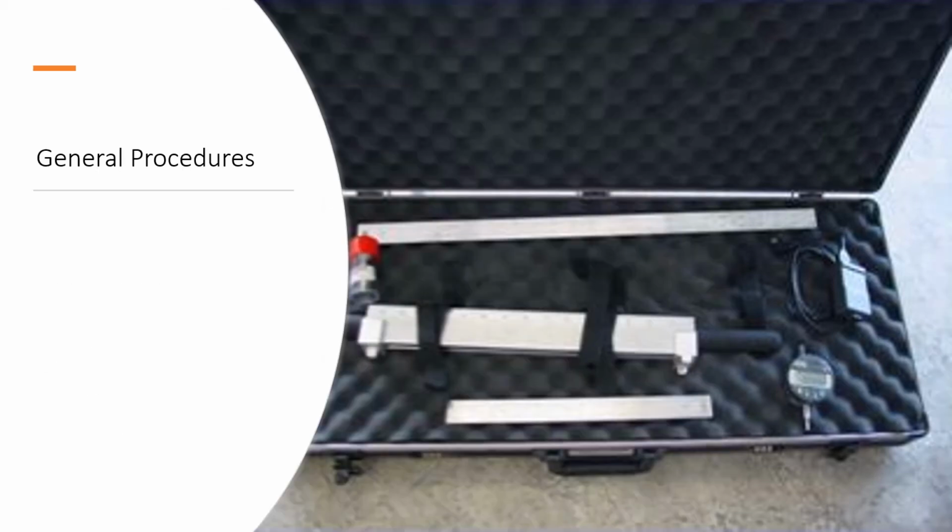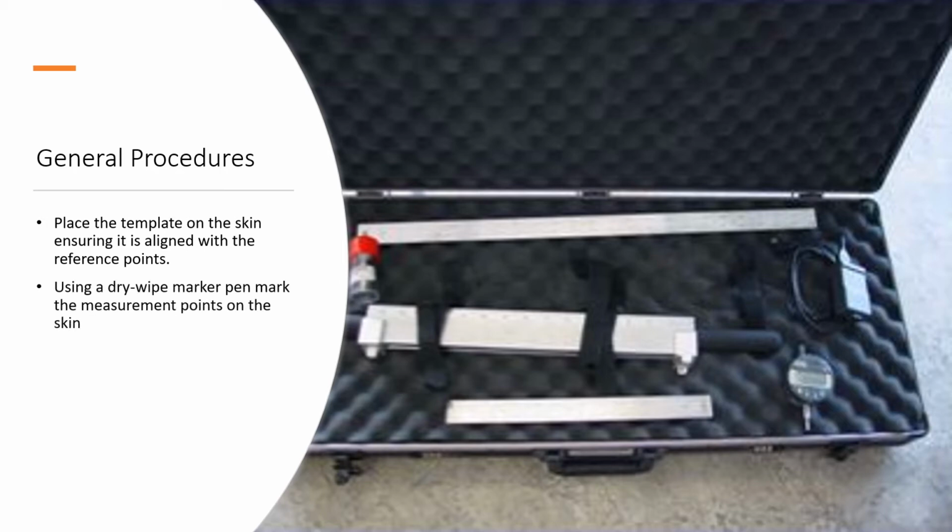So you place a template on the skin, taping it in position, making sure it's aligned with the reference points, and then using a dry white marker pen, mark the measurement points on the skin, and then remove the template.